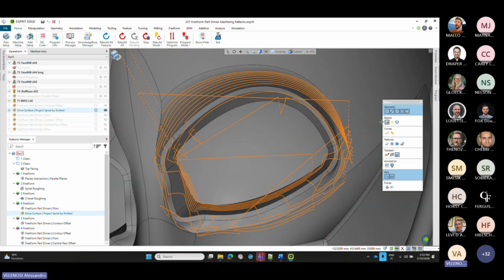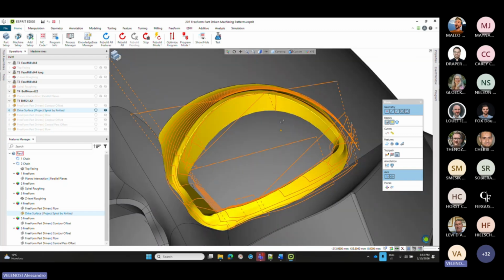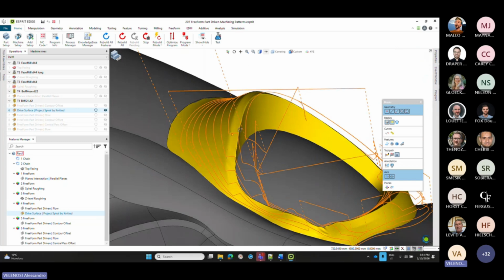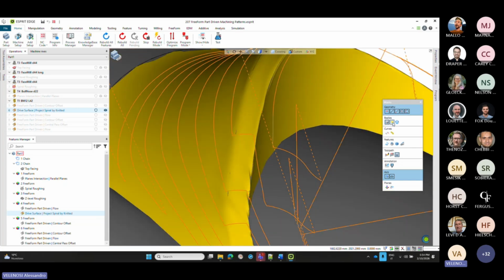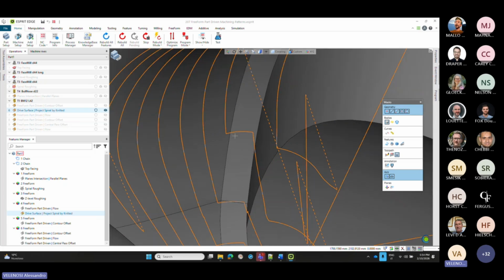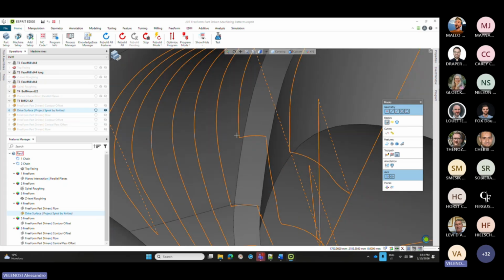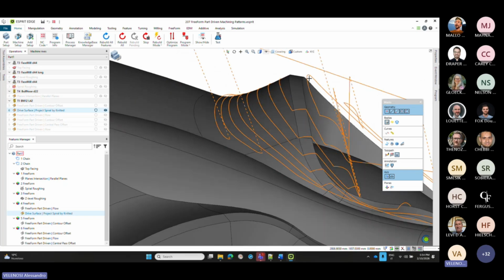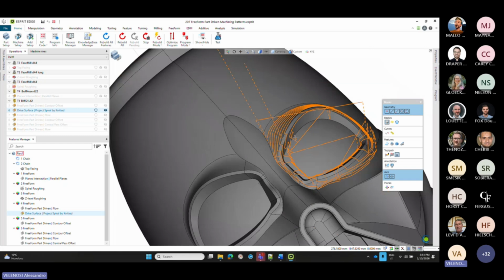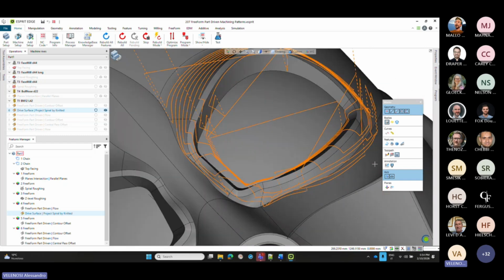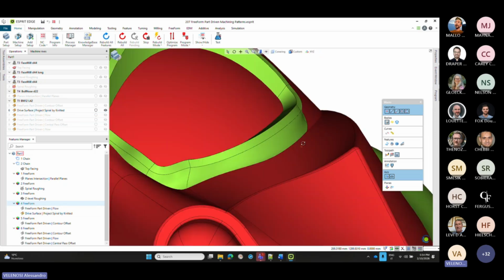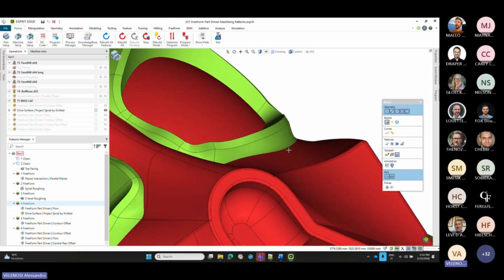We can observe the previous toolpath created by the knitted surface approach, and we can see some defects here and there. We can also highlight them. For example, we can see that the toolpath is not regular when the tool is called to move across some sharp edges that can exist on the machined surface. But also we can see that the toolpath is interrupted in the border between the part and check, because we have here a bitangency condition.